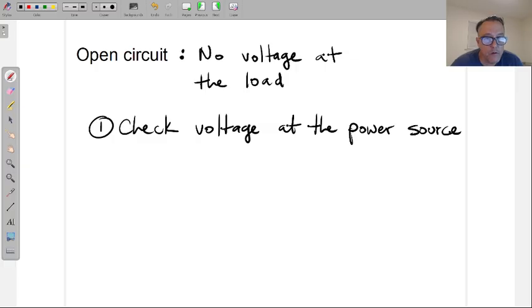Now, what is the power source? I don't know. If you're in a home, then there's no option. It's a breaker or a panel. If you're in a commercial building, it could be one of the many panels they have, but eventually you'll find the panel. If you're in an industrial setting, power sources can be a little bit different because you have control circuits. Control circuits are fed through low voltage step down transformers that convert into some very low voltages.